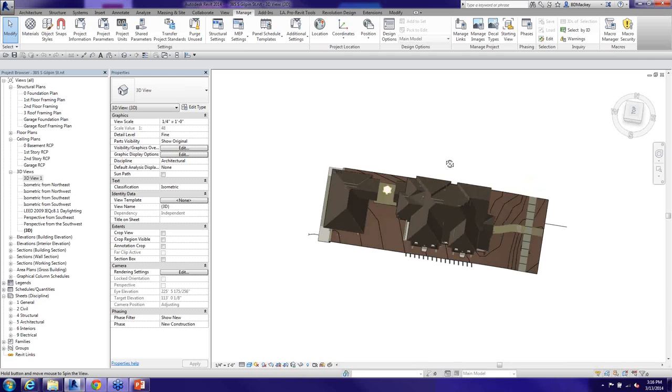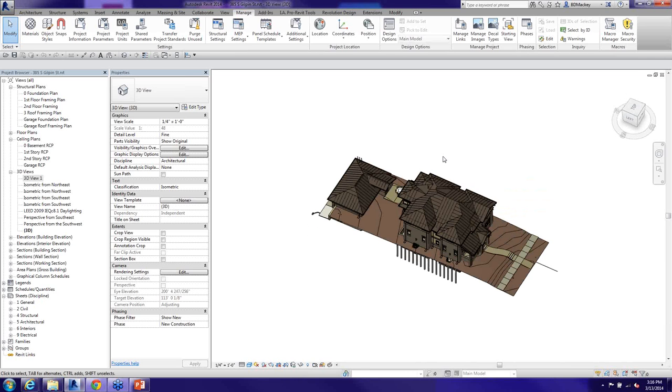Okay, the last housekeeping thing I like to talk about is if you start getting into using custom materials. So I'm going to go download a material from the carpet manufacturer or manufacturer X, or I just went and took a really cool picture with my cell phone, and I'm going to use that cell phone as the JPEG image for this. If you're in a multi-user environment, the biggest thing is most people have Revit pointing to the C drive for rendering materials.